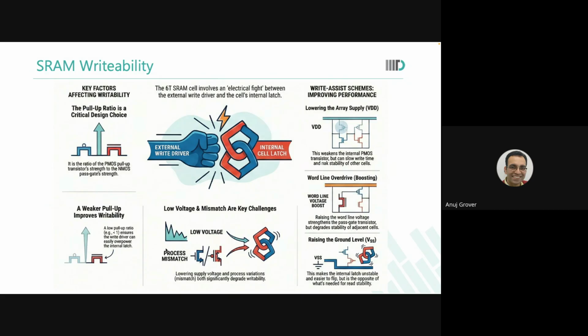Dielectric breakdown can happen. So now as a designer, you have to ensure, again, either through combinational logic or through other stuff, that when I'm operating at 0.9, I get only 150 millivolts of negative voltage. When I'm operating at 1.0, I get 50 millivolts of negative voltage. And when I'm operating at 1.2 or 1.3, I do not get any negative voltage. So I have to make it programmable now.